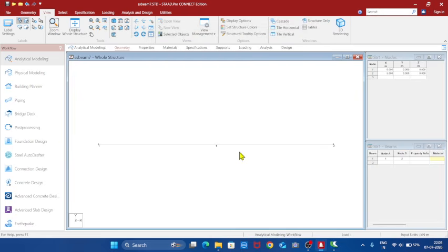Now we could see the beam number. Say beam number is 1, node number is 1. This is the second node, so node number 2, and this black dot indicates the node points. Since we have selected node points, node numbers, beam number and load values, it will be displaying whatever things we have selected. So now we have created the line model of the simply supported beam.